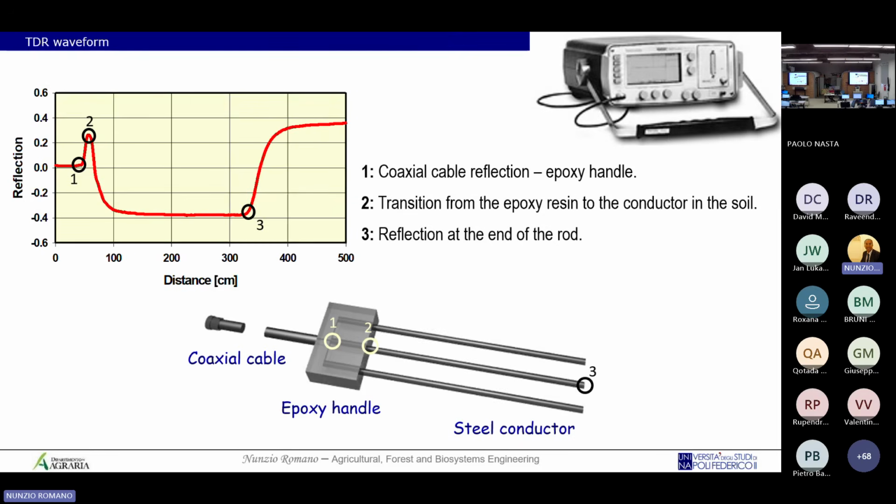You can see again in the top left of this slide, what we measure is the distance in centimeters, but the time is the same from point 2 and point 3. So this is why I say that what the TDR measures is this waveform and not just a value on a screen. So this is why, again, it's important to acquire the waveform.